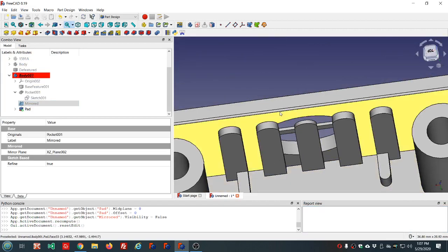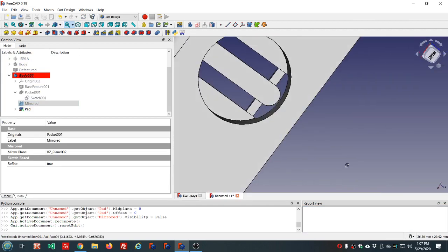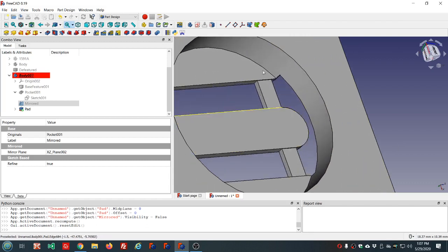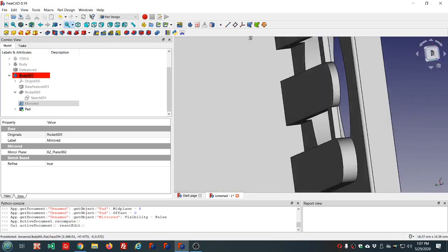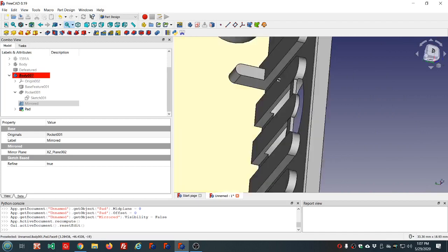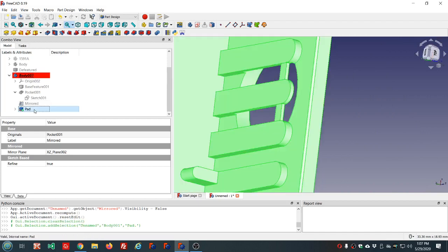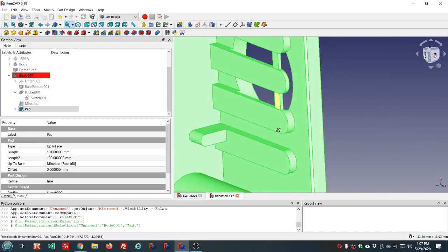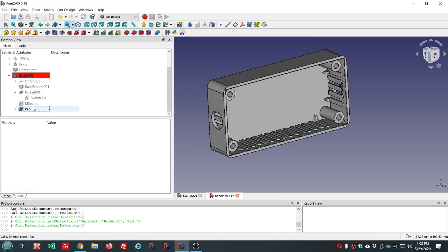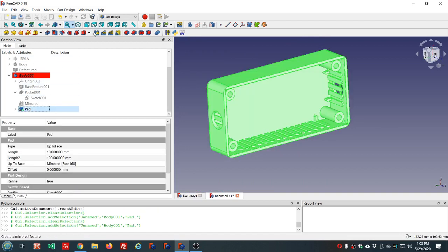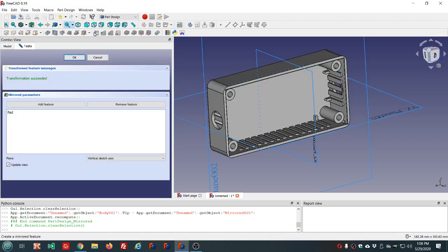And so that would be still providing the full 2.5 millimeter depth and also supporting this middle piece if you wanted to do that. Notice I selected up to face and selected this face as my destination. And now we need to do the other side, which we could also mirror over. And that was the XZ plane.